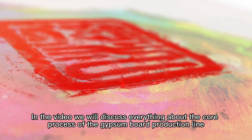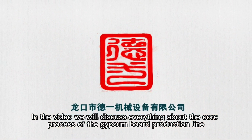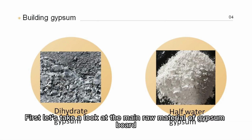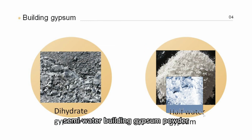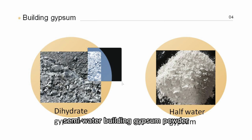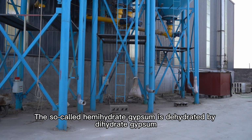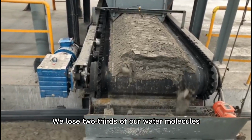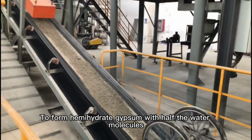In the video we will discuss everything about the core process of the gypsum board production line, and more. First, let's take a look at the main raw material of gypsum board: semi-water building gypsum powder. The so-called hemihydrate gypsum is dehydrated from dihydrate gypsum. We lose 2/3 of the water molecules to form hemihydrate gypsum with half the water molecules.